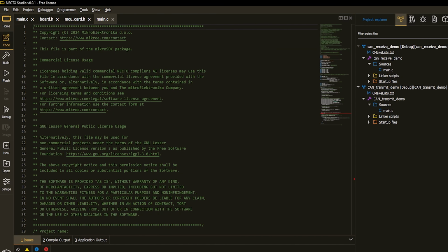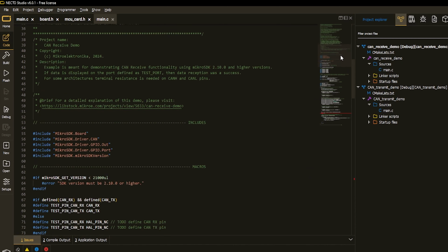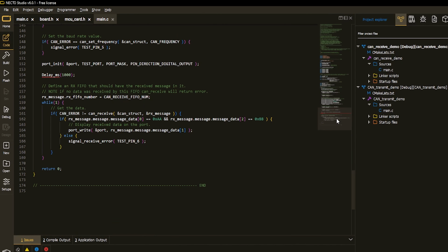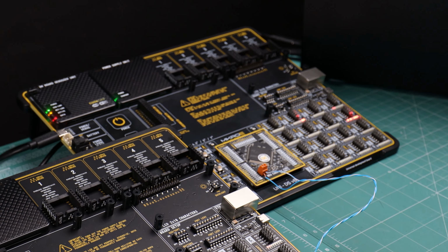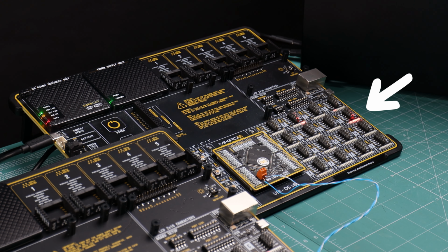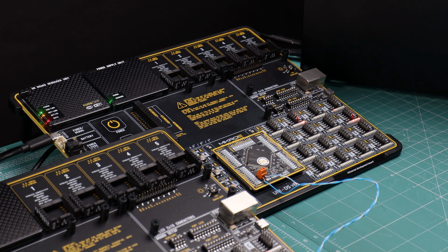Okay, that's it. After properly configuring the CAN receive project, I am presented with the demo, which is going to perform a double check of the dummy data being sent by the transmit device. And finally, this demo will display incremented values on the designated port of the microcontroller, which is labeled as the CAN receive microcontroller. What port are we talking about? Well, I will utilize port E, for example. Okay folks, that's it. After flashing the code for the CAN receiver, this is the result. A nice, useful and simple demonstration of CAN bus, which you can build with ease.